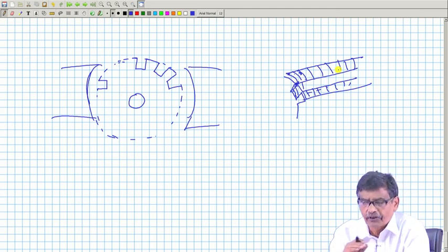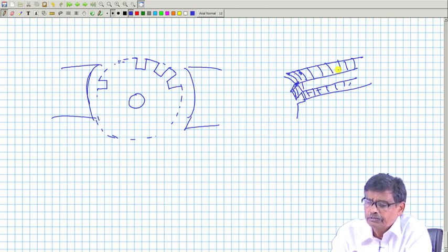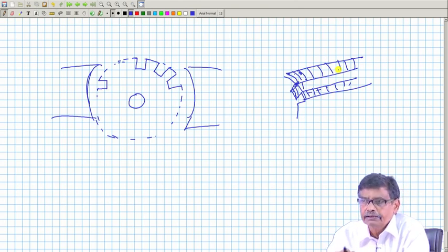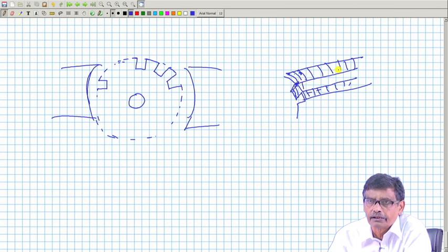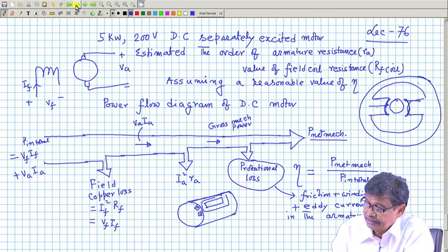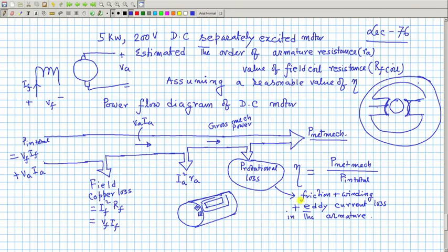But nonetheless, for a given field current, if you are not touching the field current and suppose the speed of the machine is constant, then the eddy current loss will practically remain constant. So, also frictional loss. Therefore, this part rotational loss consists of friction, windage, not winding, I am so sorry, it is windage, it is called windage loss. This is the scenario of the machine.